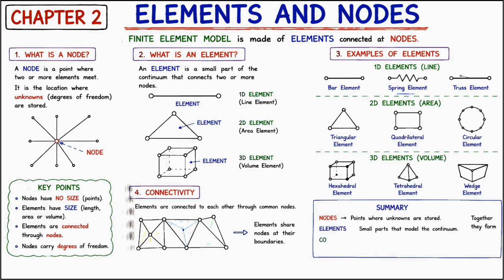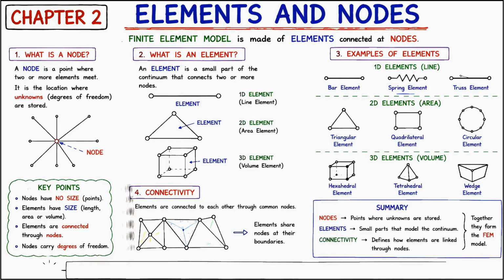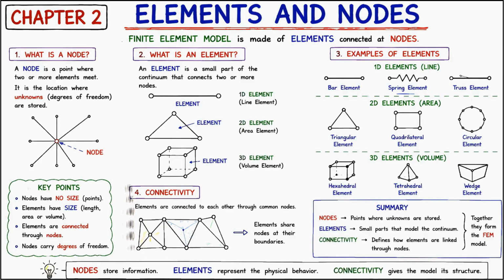So always remember these 3 key concepts. Nodes store the unknown values. Elements represent the physical behavior of the structure. Connectivity links all the elements together to create one complete finite element model. These are the fundamental building blocks of the finite element method.